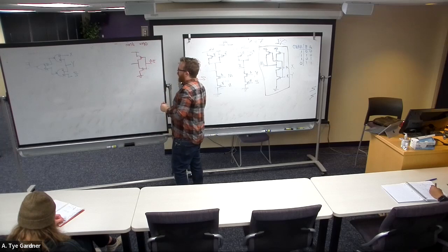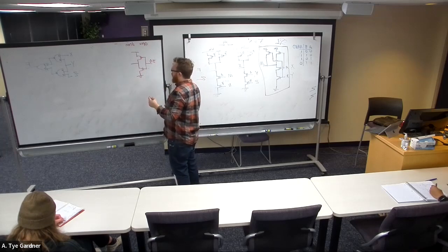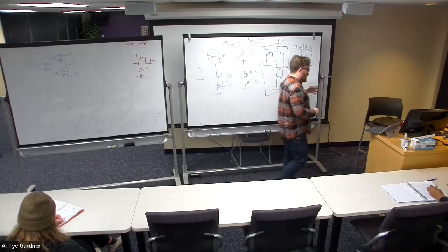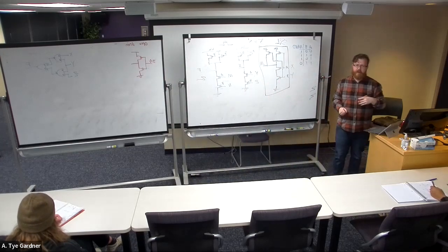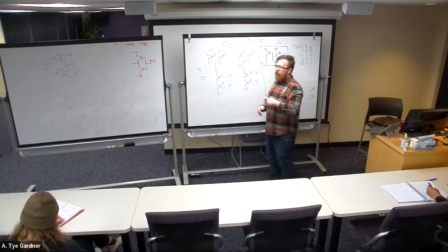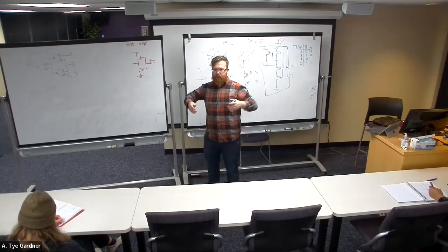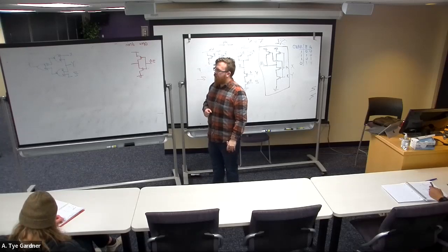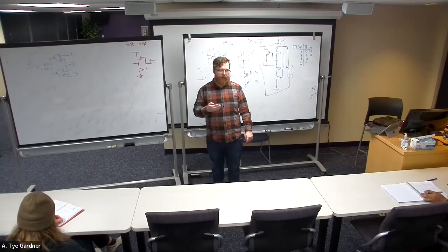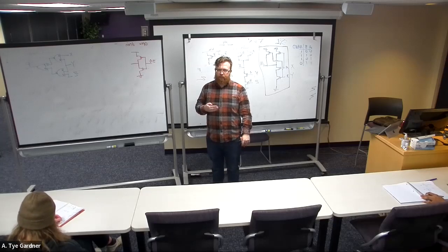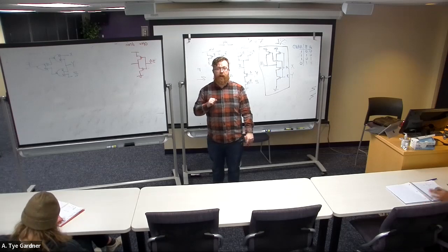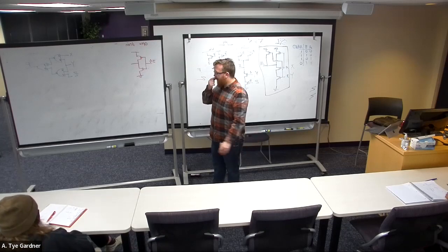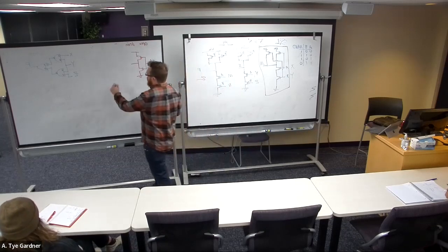That's my output signal. And I want to say something like, okay, we only want to be able to assert zeros is how I'm going to phrase this, okay? Because what's going to happen is I don't want my circuit necessarily to be able to drive a 1. So we're going to use a pull-up resistor. We're actually going to bring this back because it's very helpful to have a situation where